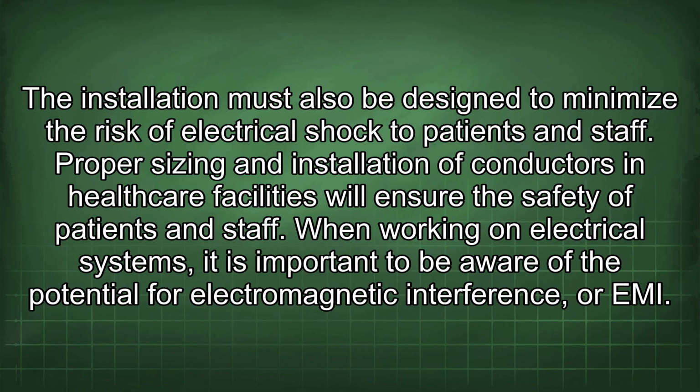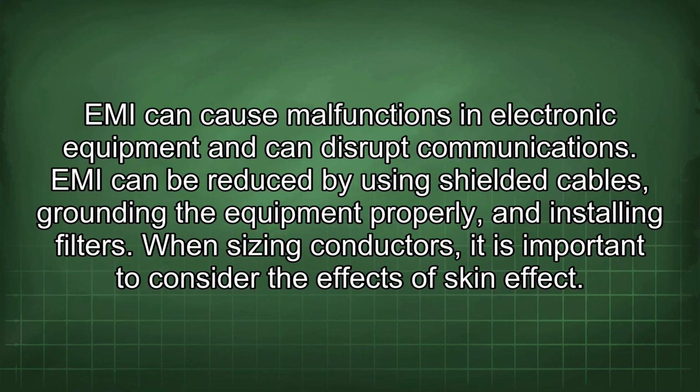When working on electrical systems, it is important to be aware of the potential for electromagnetic interference, or EMI. EMI can cause malfunctions in electronic equipment and can disrupt communications. EMI can be reduced by using shielded cables, grounding the equipment properly, and installing filters.